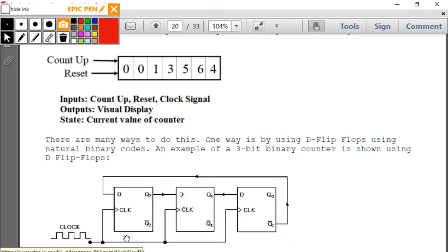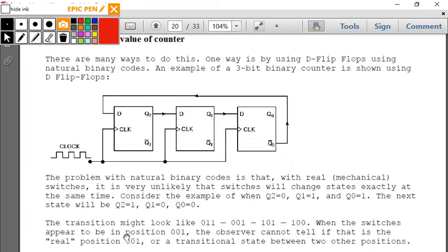That signal will change. And the whole idea is that you go in binary up counter, 0, 1, and then once it goes to 0, the next one goes to 1, 1, 0. One of the issues that we're going to come across here is what happens when we have Q2 equals 0, Q1 equals 1, and Q0 equals 1.